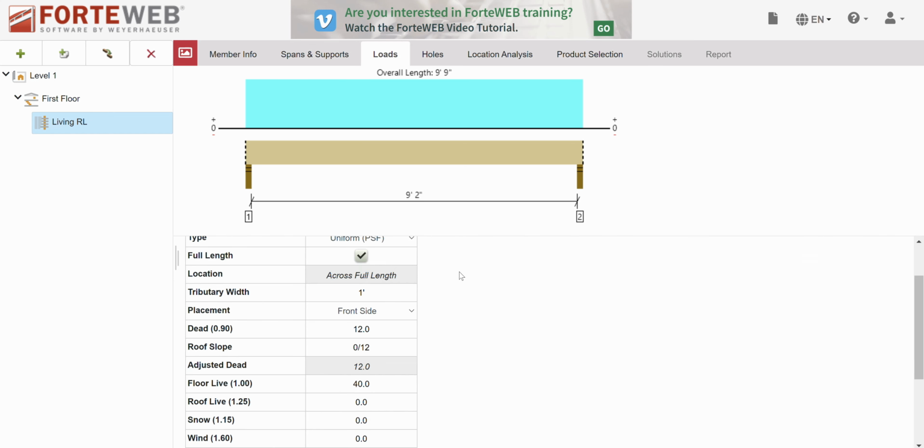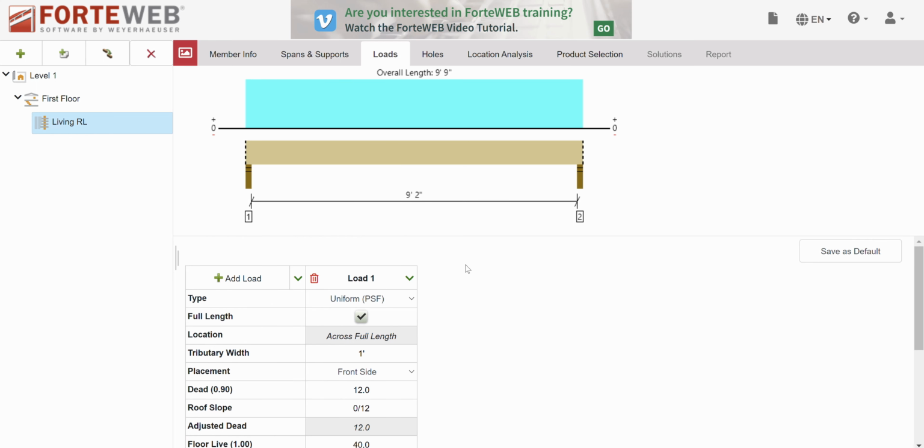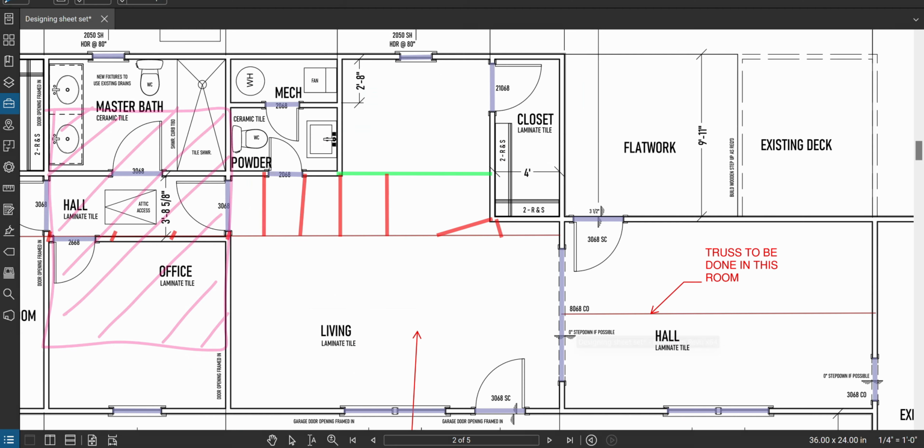Now, how are we loading the beam? All right, so here's where we get into the numbers. So we're going to go back and ask top down, what are some of the loads we know are happening here? Well, let's deal with the roof brace last, because that's a roof weight. And I'm not concerned with the roof weight that's here, because it's going to be either put straight on the wall, or it's going to go on the top of the beam, which is going to go straight through it onto the wall. Not going to stress the beam. So I'm concerned with this roof brace, and I'm concerned with the ceiling joists over on this side and the ceiling joists on this side. They're both putting weight on this guy.